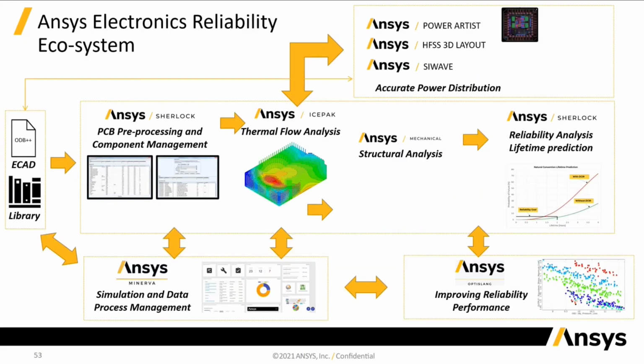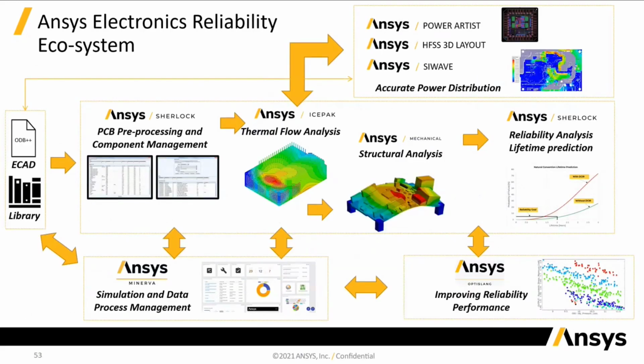Okay, and then just one final slide. Sherlock is one of a series of tools that can be used within the ANSYS PCB reliability portfolio, if you like. I've already mentioned SIwave for signal and power integrity, and Icepak. Sherlock can be used to export the 3D model it creates out to Icepak or out to ANSYS Mechanical, and thereby you can incorporate broader concerns, so maybe particular types of housing or special cooling that you want to incorporate, and that information from those tools can then be fed back into Sherlock for a refined reliability analysis.